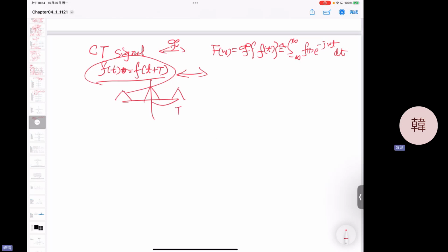You have to remember this repeat signal, repeating with a time of T seconds. As I told you, every repeat signal becomes a Fourier series. Why? Because the repeat signal can be decomposed into different harmonic waves. So the Fourier transform becomes like this, a spike spectrum.